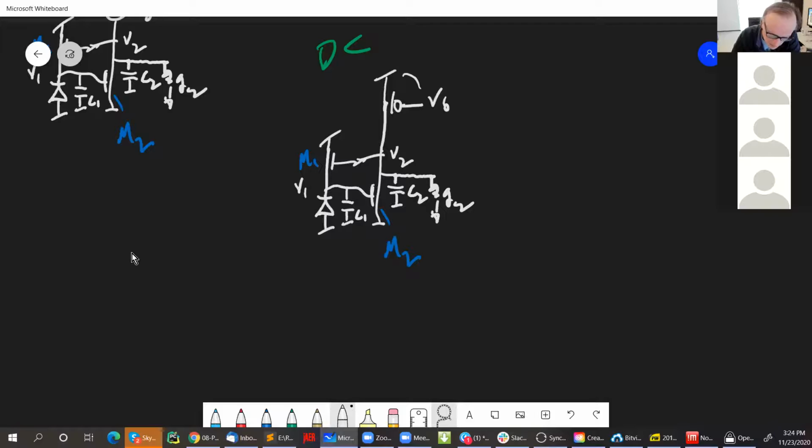And then if we want to calculate the actual voltage here at this node, we need to know what the photocurrent is. So since we already said that the photodiode acts like a current sink, let's replace this so we can actually compute the voltage. Let's replace this with a transistor. And you know that a transistor acts like a constant current source or constant current sink as long as it's in saturation. And by putting a transistor there, we can put a voltage on the gate of that transistor, V0. And now we have voltages, right? We don't have any currents to worry about. So let's reason about what V2 and V1 are.